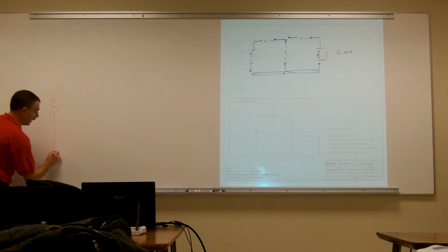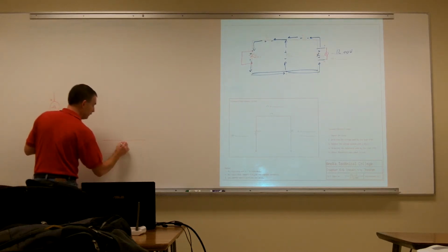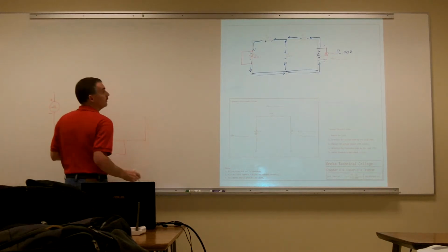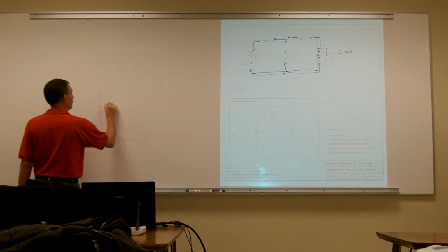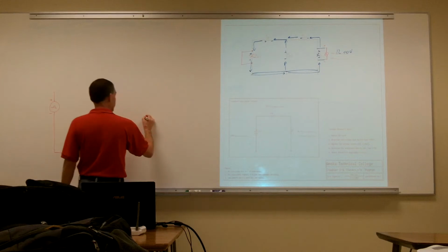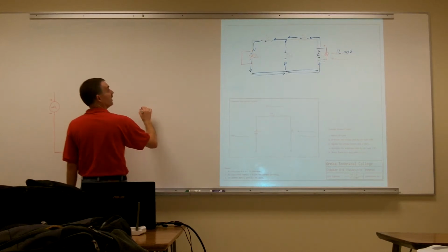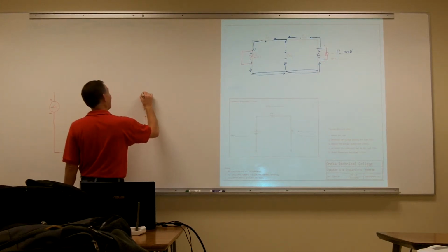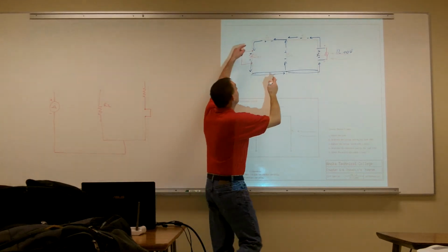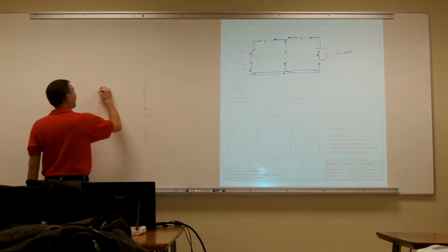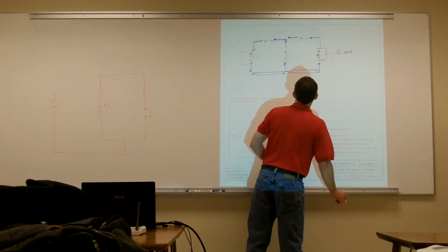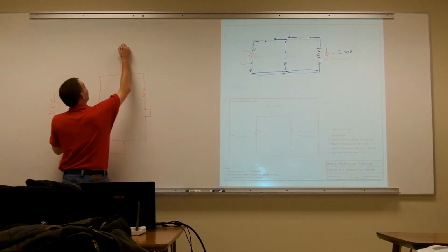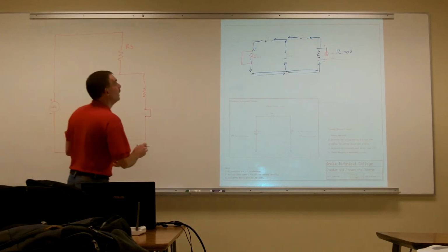So the negative side of my ohm meter is coming down, going through the ground, it's coming up. It's going to split. Some of it's going to go through R2, and the remainder is going to go through the shorted out power supply. We'll just draw that in there so we know where that's at. And then it's going to go through R1. Then those two currents are going to combine back together, and then all my current is going to go back through R3 and back into my ohm meter. So then I'm going up to R3, back down. Now I have my R3, and it's R1.